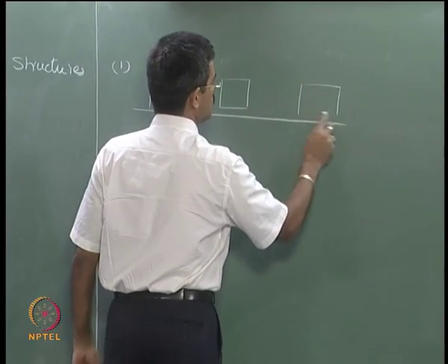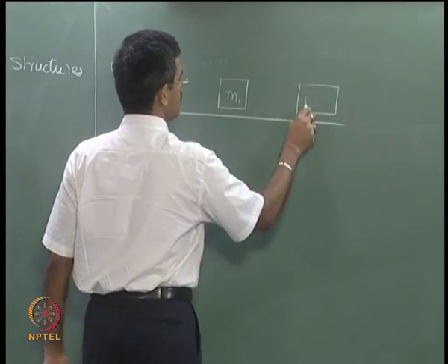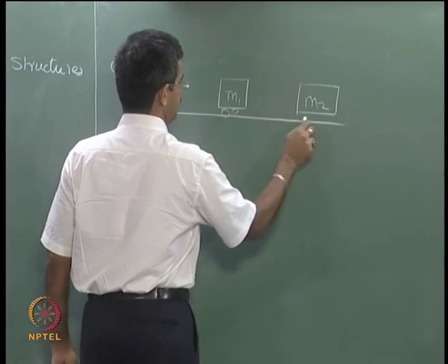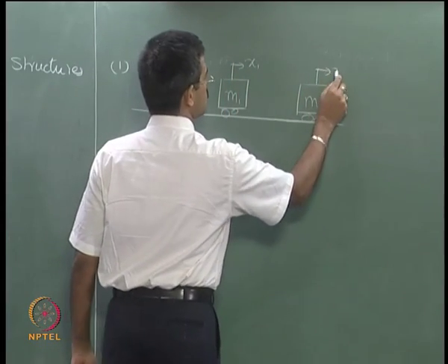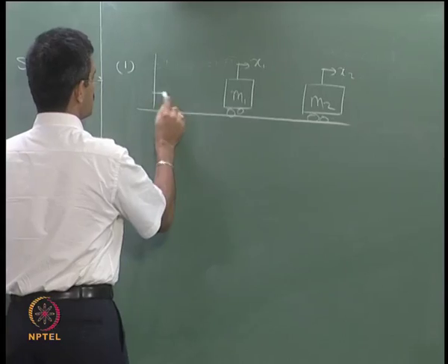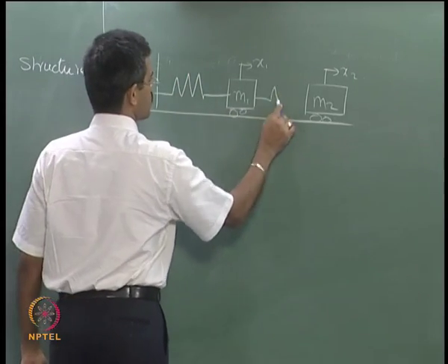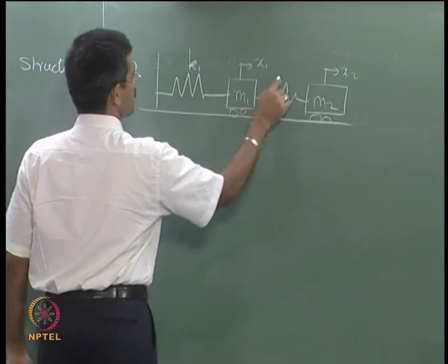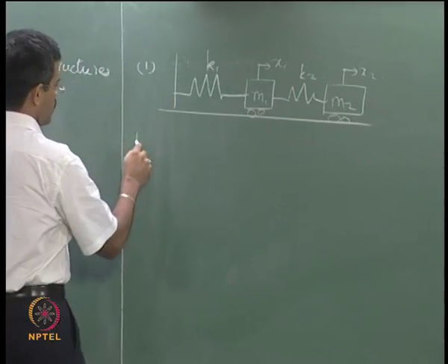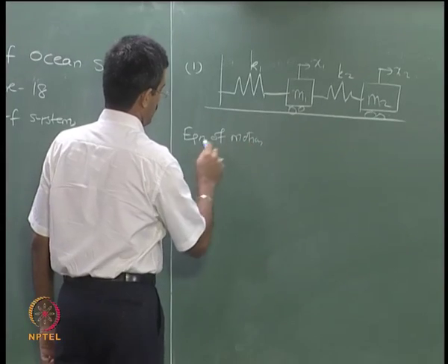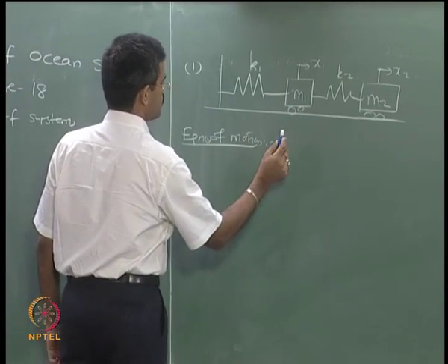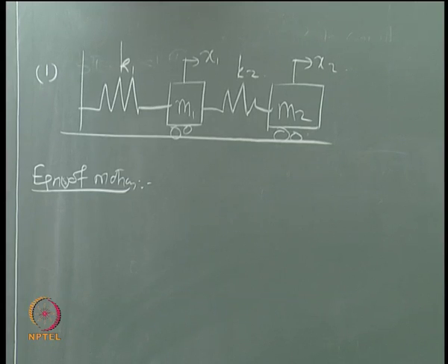Let us say I have two lumped mass points M1 and M2. From the CG of M1 and M2, I measure the displacements and imply upon the restoring forces, call them K1 and K2. I want to write the equations of motion for the said problem. So I will use Newton's law to do this. I will also solve this problem, or a parallel problem, using the energy method.